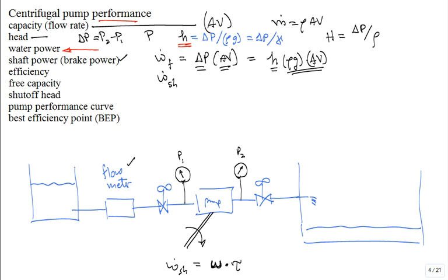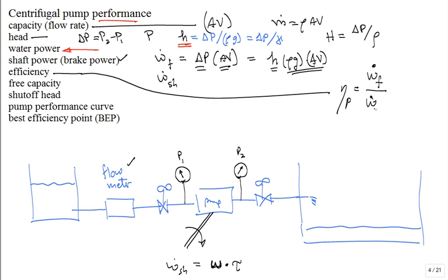And we know the shaft power is going to be greater than the fluid power, and the ratio is the efficiency. So the efficiency right here, I'm running out of room. Let's say the efficiency of the pump is the W dot that gets where you want it to go into the fluid divided by W dot shaft that has to drive the pump. That's the efficiency.